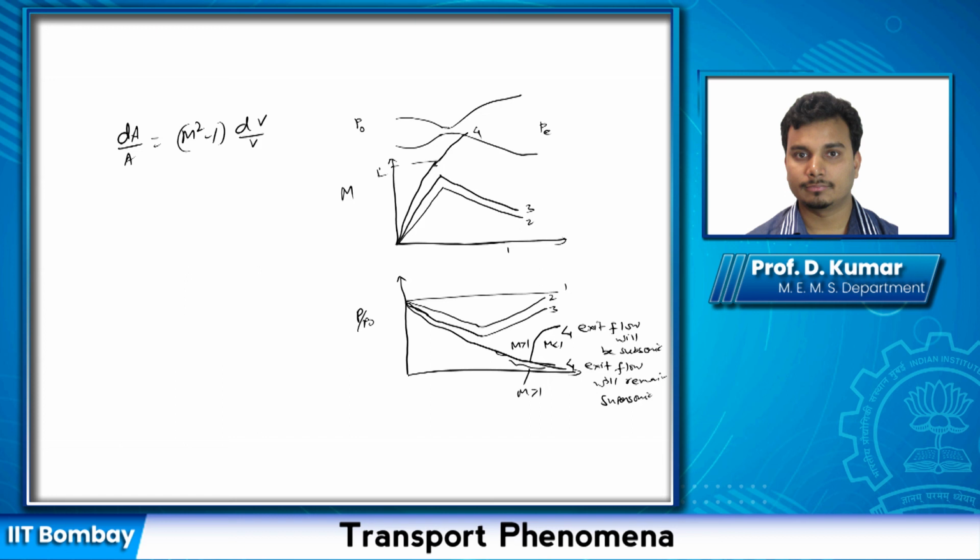In steel industry, for example, we use supersonic nozzles so that we can do the BOF operation very quickly, and so on. So even on the process side, in manufacturing processes, for example, in gas atomization for metal powder, supersonic jets are very important.